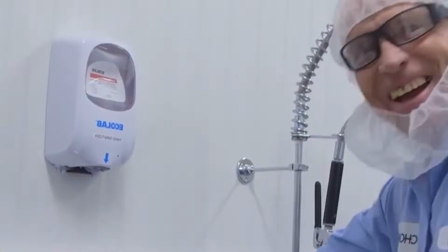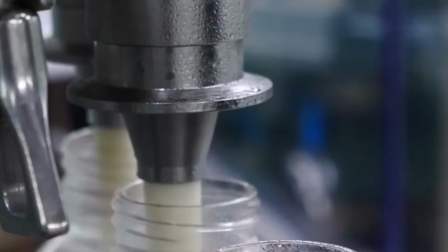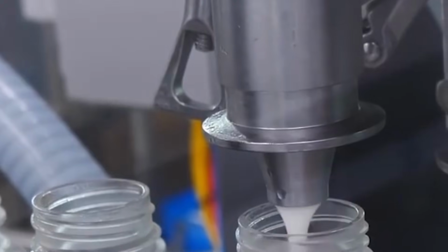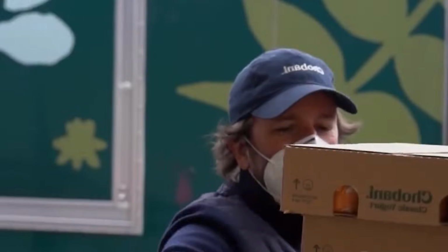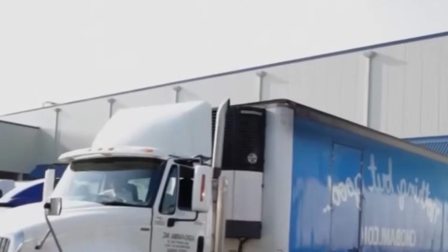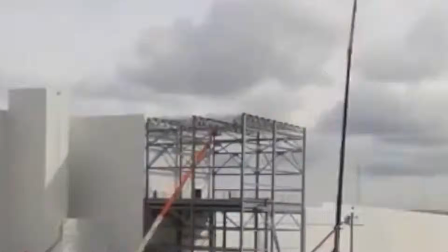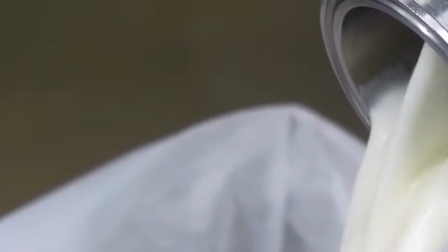The homogenized mix is rapidly cooled to 4 degrees using a plate heat exchanger and transferred into agitated aging tanks. These stainless steel tanks have capacities ranging from 2,000 to 20,000 liters and are equipped with low-speed paddles to maintain uniform suspension without introducing air. The mix is aged for 4 to 24 hours depending on the formulation. During this aging period, fat crystallization and protein hydration take place, improving the whipping properties and final texture of the